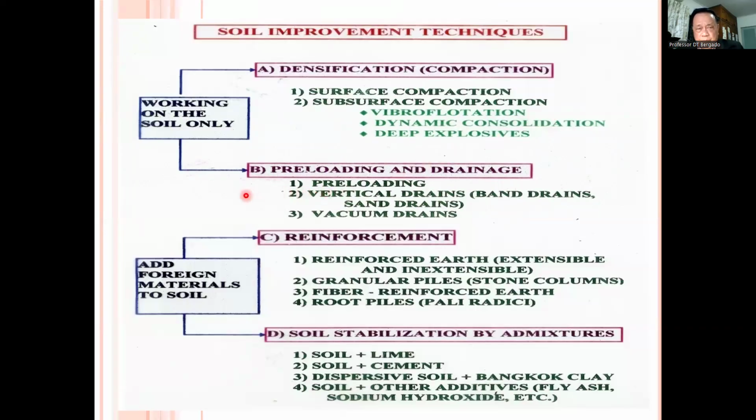If we have fine-grained soils, we cannot use force to reduce the voids. We have to use drainage, where vertical drains or vacuum PVDs are used.